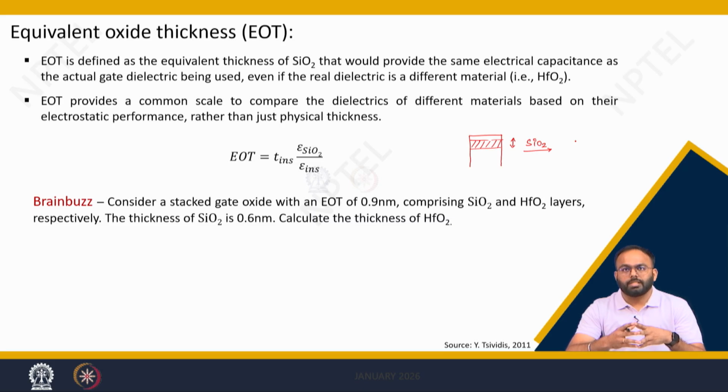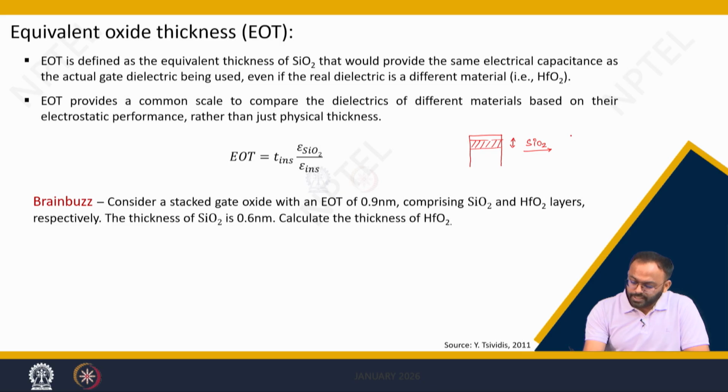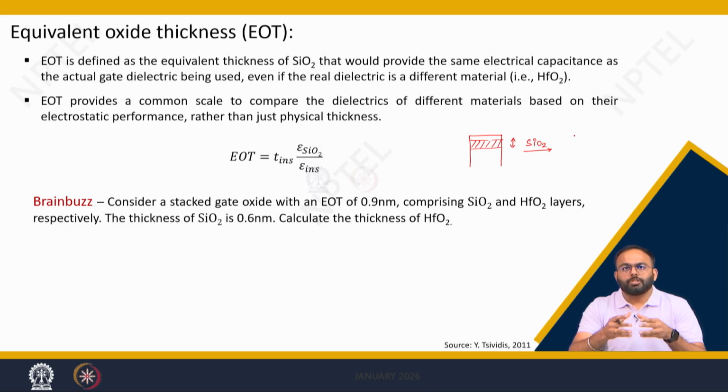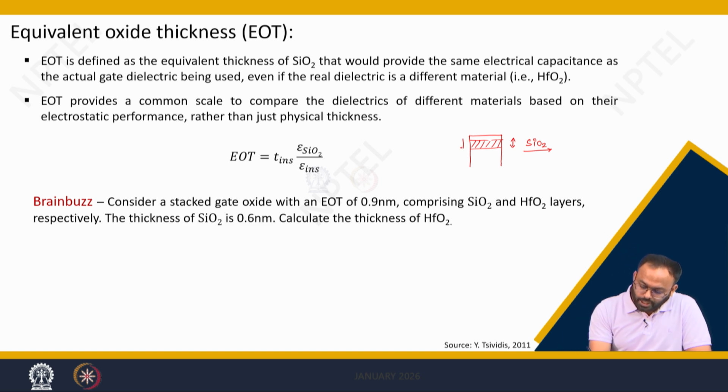That layer comprises some high K dielectric such that the physical thickness of the oxide layer is improved. When you follow a scaling rule, it is not always true that you can scale only one dimension and leave the other untouched. You need to scale the device thoroughly, and that pushes the scaling limit of silicon dioxide.